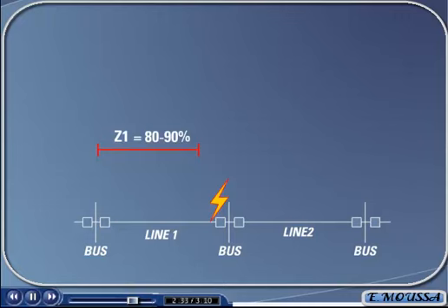The permanent fault would then be cleared by the Zone 2 protection after the set time delay if the fault fell inside the transmission line's end zone area. If the permanent fault was picked up by the relay Zone 2 because it was located at the beginning of the next adjoining transmission line, the relay protecting that transmission line would pick it up in its Zone 1 of protection and clear the fault.